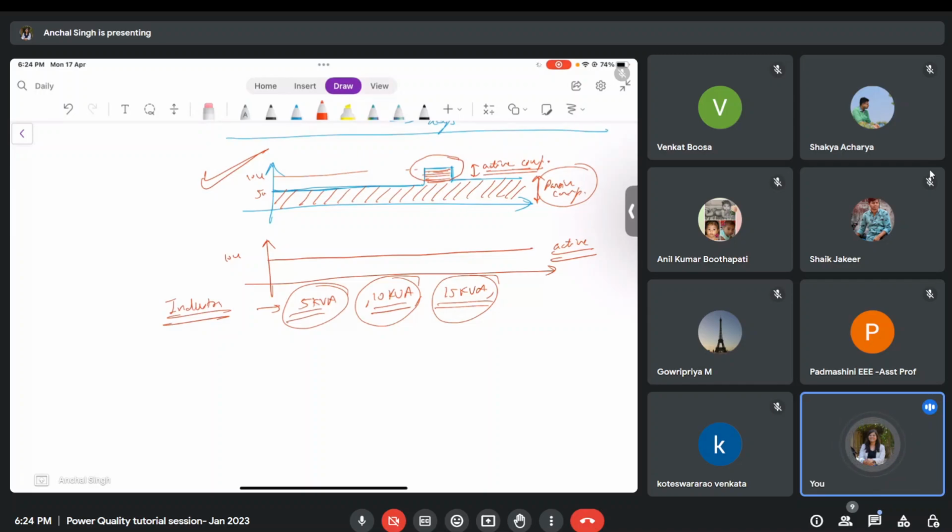All sorts of reliability studies are done, on how long these equipments will be working. A lot of engineering is involved in that. But this is the whole procedure. There is no standard generalized solution for any power quality problem. You have to first look at the problem and at the kind of electrical power consumption, and then based on that you can decide which kind of solution you want to take up.